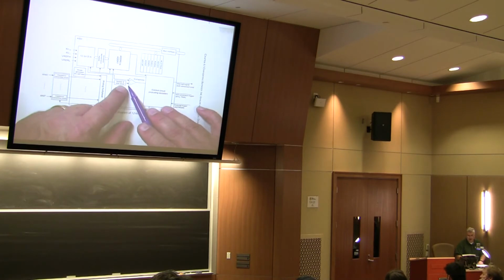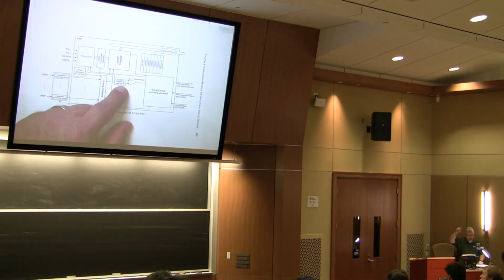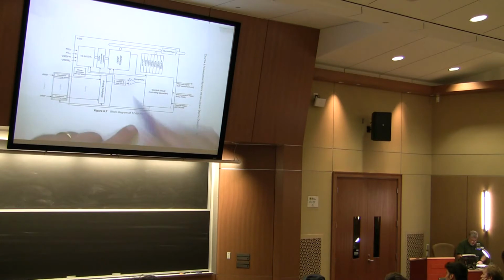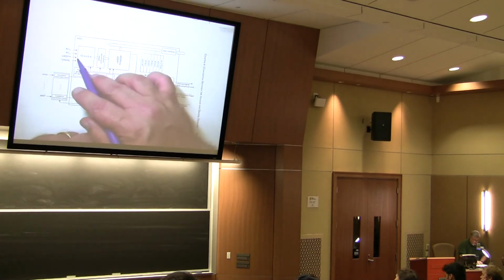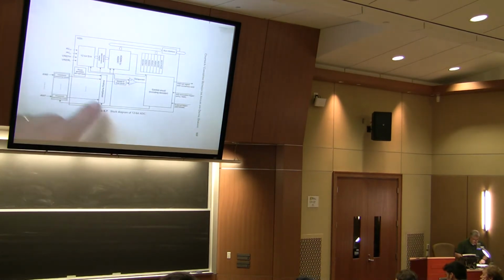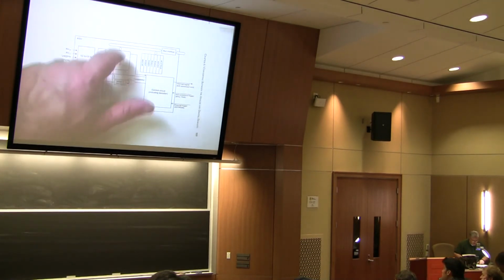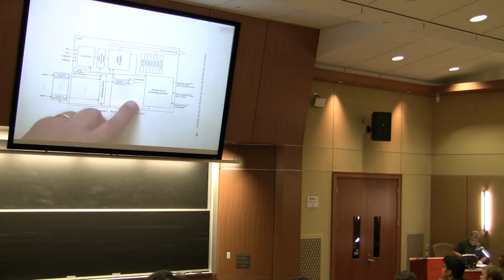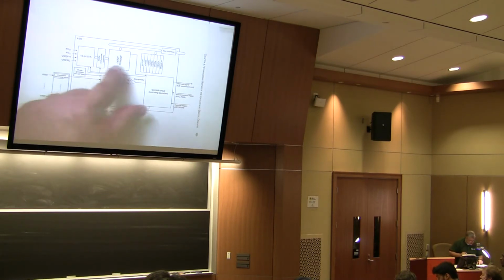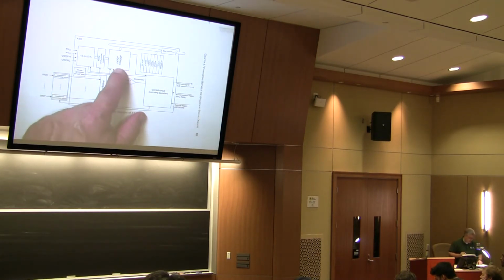Sample and hold means that an analog signal could be varying quite a bit, so at one point in time we say, all right, that's my snapshot. I'm going to take a picture of that. In other words, I'm going to hold that voltage, and then do some converting. Then it goes to the controlling circuitry for comparing, and once it's compared, it will be stored into your registers.